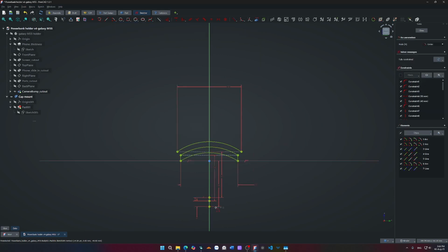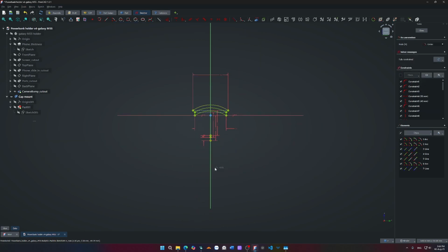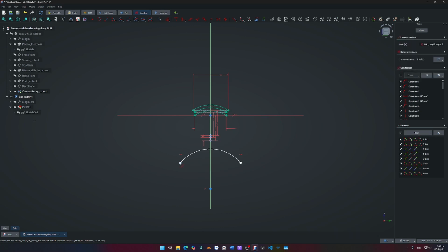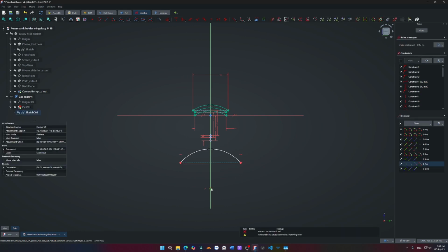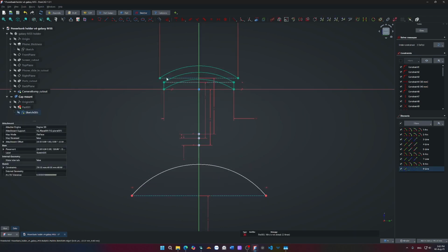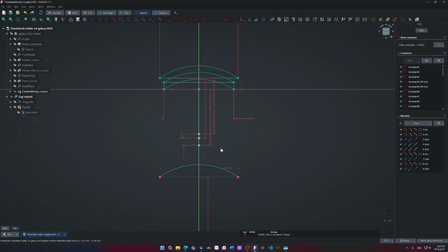GA. Oh, nice. Makes sense. G and arc. Generate arc or something like that. This one should be horizontal. Nice. GN, GL. Actually, do I need the GL? GL. I think I do need it to set the distance from here to be 40 millimeter as well, and this line and this line need to be equal. Right, they are now equal.